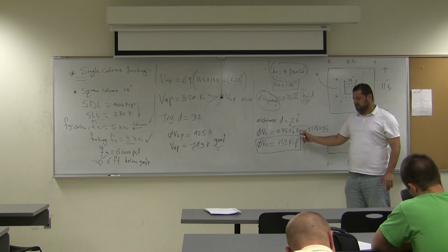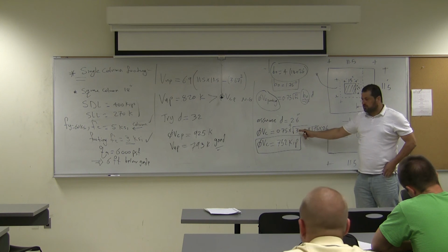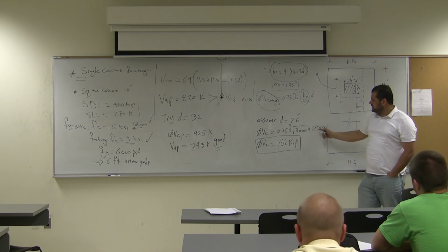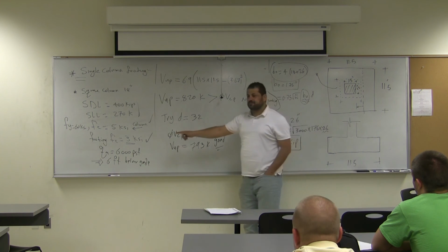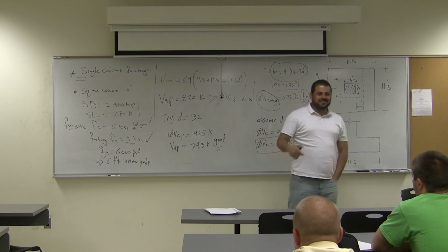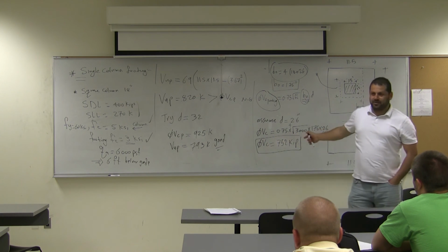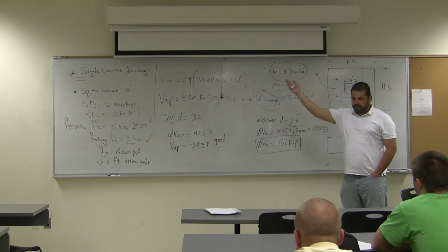This one was 4,000. So, square root of 4,000 times 176 times 26 times 4 times 868. That will do it, by the way. Yeah, just barely. That will do it. And it's easy to get 4,000 psi concrete. Okay, just to let you know when you go out and work.